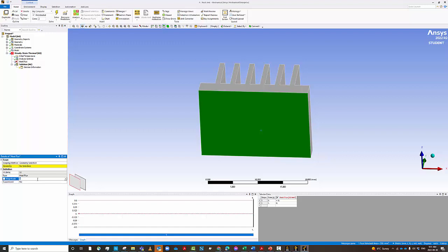You have to convert it, and I made the mistake earlier, and I thought, if I want to convert watts per meter square into millimeter square, I multiply it by 10 to the 6, which is wrong. You have to divide by 10 to the 6, right? Because you want to change meters to millimeters. 1 meter is equal to 1000 millimeters.